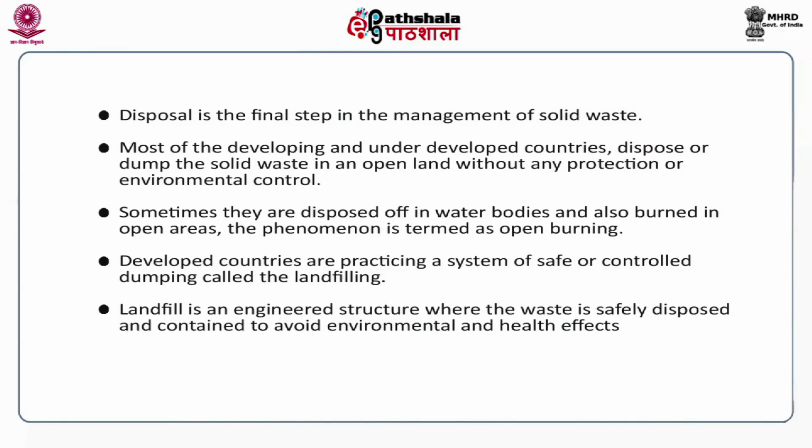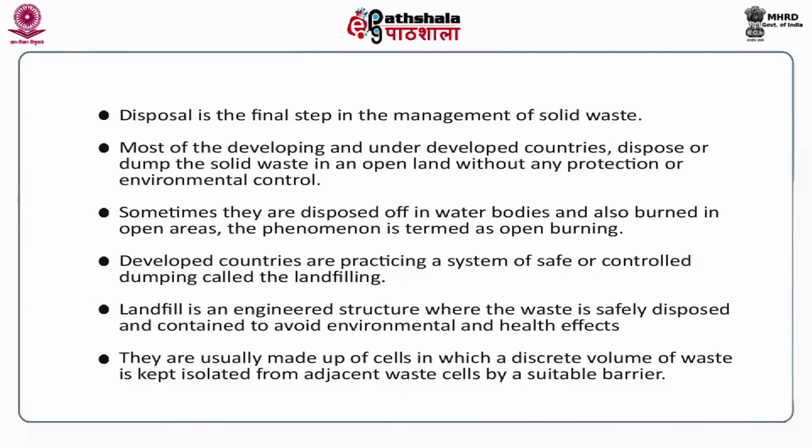Now, as I told you, landfill is an engineered structure where the waste is safely disposed or contained to avoid environmental and health effects. They are usually made up of cells where a discrete volume of waste is kept in isolation from each cell. What I mean to say is the landfill is divided into imaginary cells where the waste is loaded and separated from the adjacent cells by a suitable barrier.